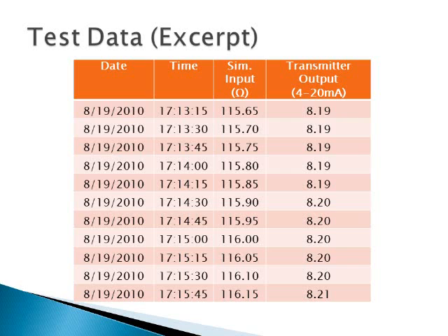And what you observe is that the transmitter is really able to make a change in any difference only when that value changes by 0.25. It detects a change when there is a change in the point of more than 0.25, and this is the 4 to 20 milliampere output. So that is 20 minus 4 by 4096 that comes, and that again depends on the precision of the output measurement. So we find that we do not really need to check for these types of inputs.